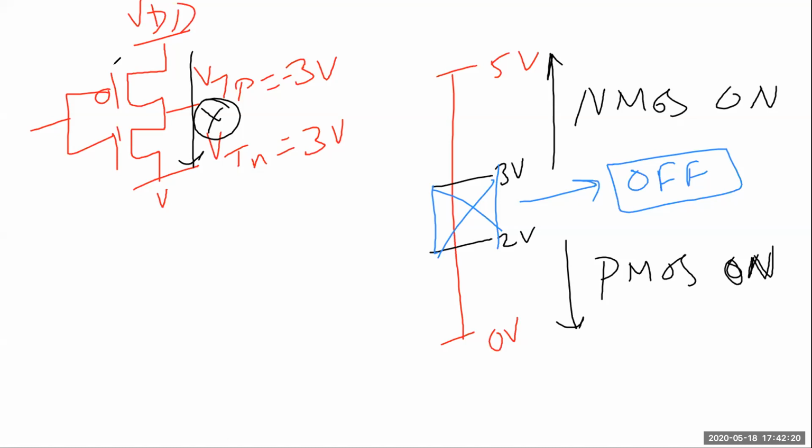What I wanted to show was a dynamic curve, because statically you get a hysteresis. You go from VDD to 0, and then from 0 to VDD, but there is a dead region. When you're going from VDD towards ground, you'll see the PMOS take over after some time, after 1 volt.